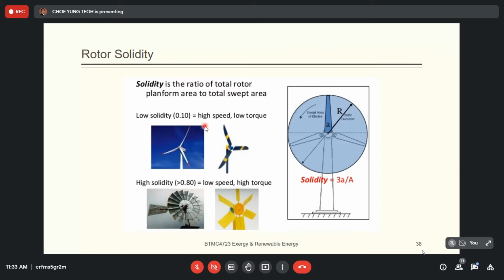But actually for a normal wind turbine blade, even with three blades, it will rotate at just around 30 to 60 rotations per minute, much slower than the rotational speed needed for the AC frequency. In general, AC current requires a speed of around 1000 to 2000 RPM. So of course, we are not able to achieve 1000 to 2000 RPM on the blade.